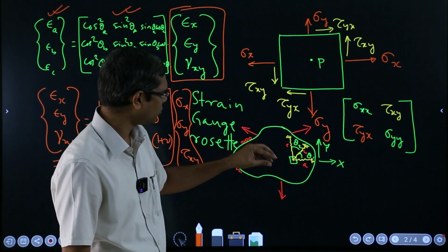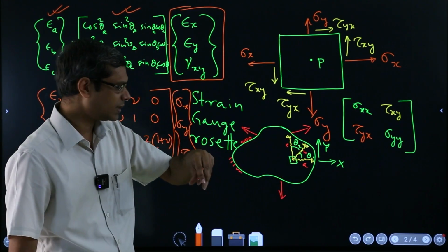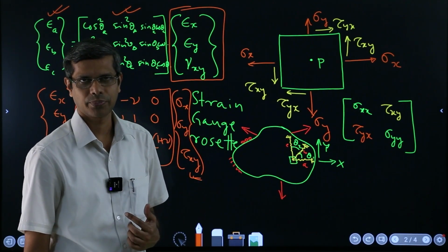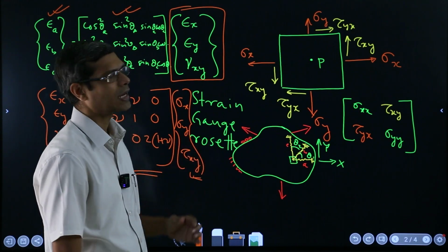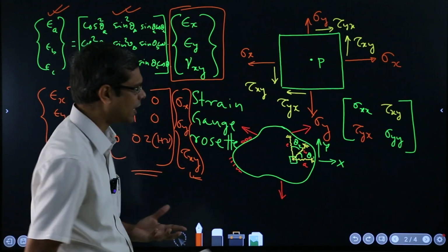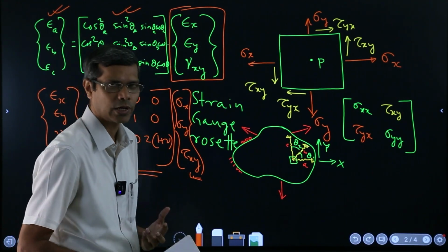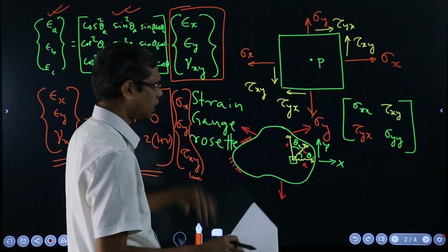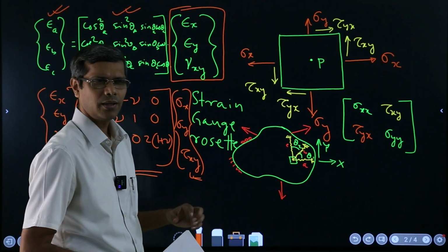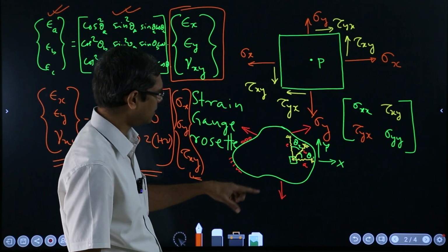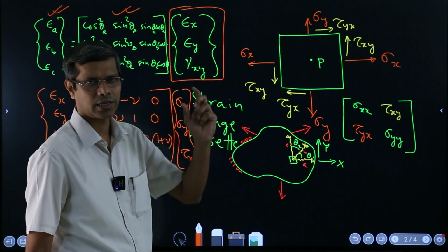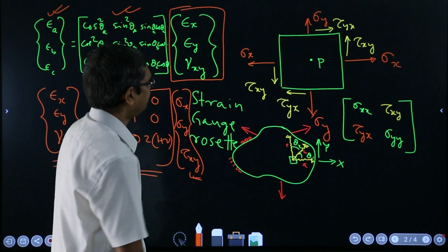So you have to keep rotating these rosettes for all the angles which you require, and then out of all those values you look for the most dangerous, the most unsafe value. But it's a very clumsy idea, you have to do it multiple times: remove it, change the orientation, put it, measure it, again do that, and it's bad.